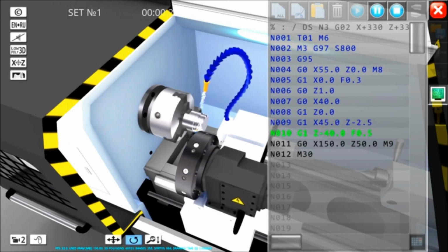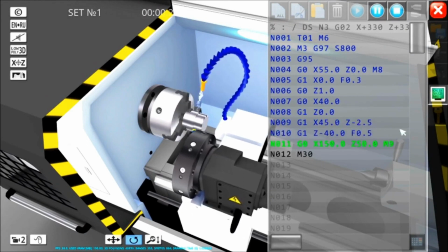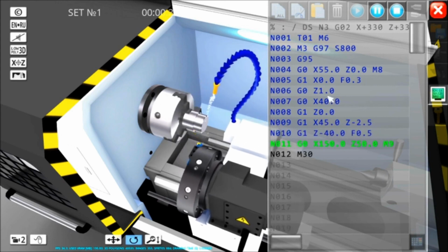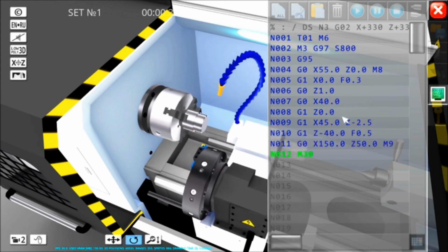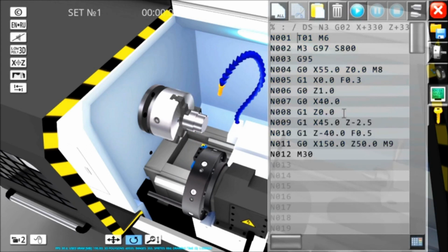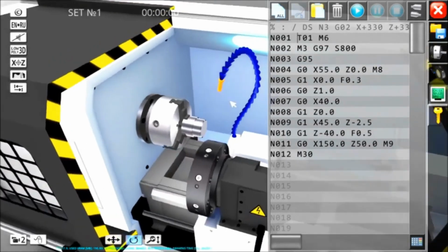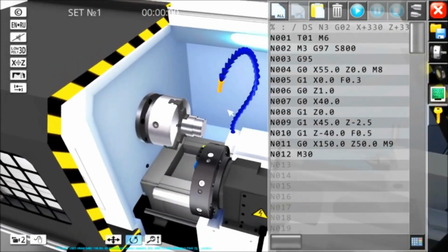Well, I'd say that we're done for now. Try to reread some of our codes. Take a square sheet of paper, mark the z-axis and the x-axis in squares with units, and make some small programs where you move in Cartesian axis space. Remember, the z is normally programmed in negative, the x in positive.